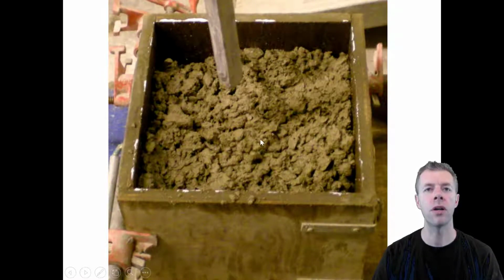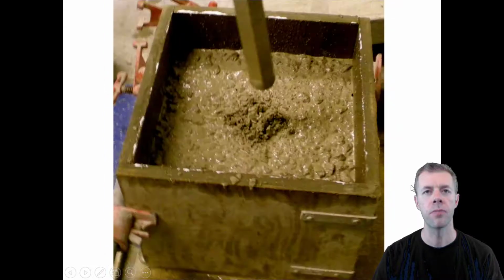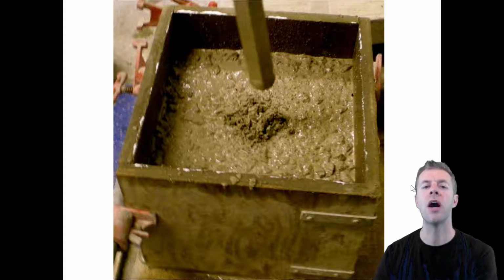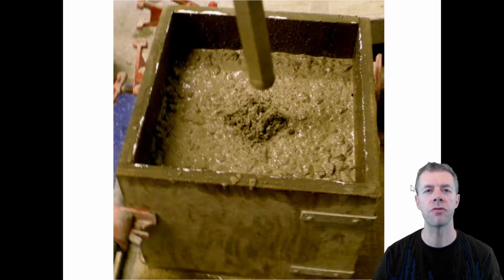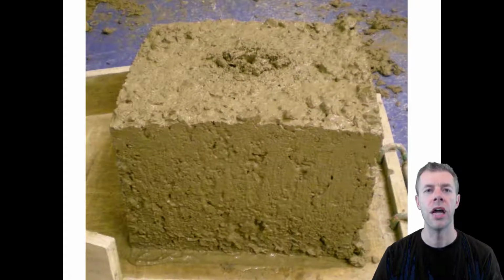Here it is. There's the vibrator. There's the box full of the concrete. Goes in for 3 and out for 3. And there it is, consolidating the concrete. And now we immediately take the pipe clamps off. We look at the edges. And we're looking for honeycombing. We're also looking for edge slumping. Let's look at honeycombing first, though.